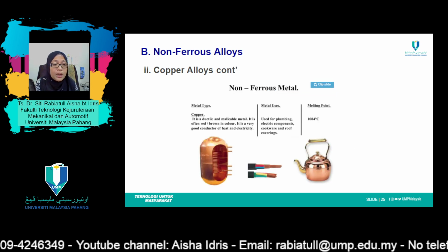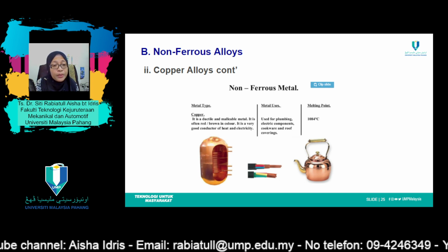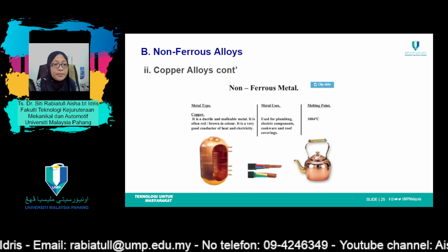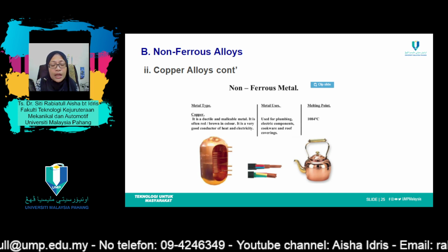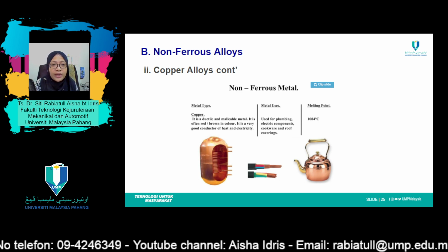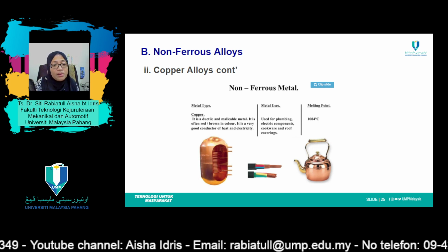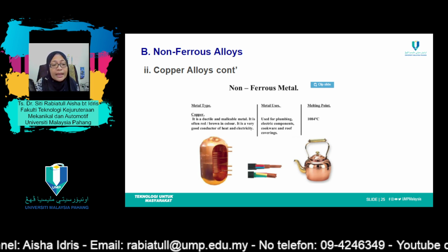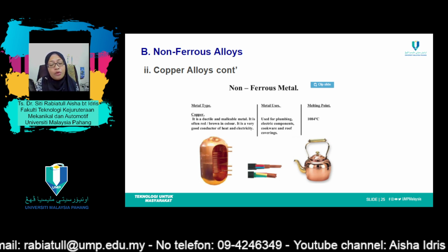The most common copper alloys are brasses, for which zinc as a substitutional impurity is the predominant alloying element. Some of the common brasses are yellow, naval, cartridge brass, and gilding metal. The applications include custom jewelry, cartridge castings, automotive radiators, musical instruments, electronic packaging, coins, and so on and so forth. The bronzes are alloys of copper and several other elements, including tin, aluminium, silicon, and nickel. These alloys are somewhat stronger than the brasses, yet still have a high degree of corrosion resistance.